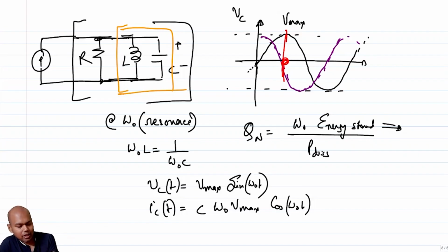In this case, I will take the instance where the current in the inductor is 0. The current in the inductor is the same as the current in the capacitor because the currents are flip-flopping between the inductor and the capacitor and not going out. So if I take the point where the total current is 0, the entire energy of the tank at all points of time can be found from the energy across the capacitor when the voltage is maximum.